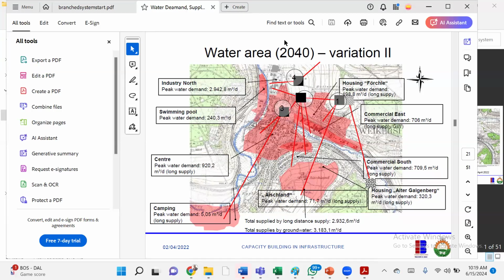And when that is happening, then you need to introduce booster stations. You need to zonalize, put them into pressure zones, and then you need to decentralize the system. Yeah. You need to create separate tanks. You can still use the same source. You can also customize it to different sources, different tanks, so that it will deliver water effectively, efficiently. Quality parameters will be met, quantity parameters will be met, and sustainability parameters must be met.